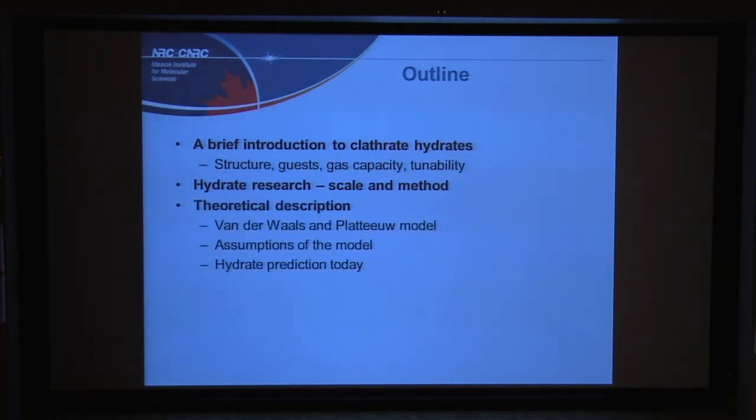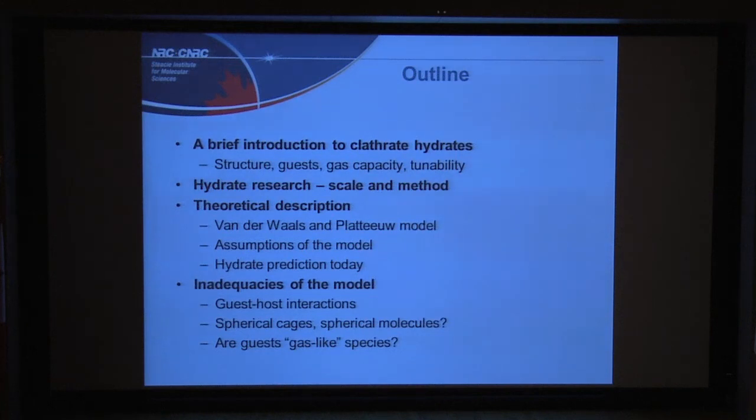Then I'd like to get on to the theoretical description. The van der Waals and Platteeuw model dates back to the 50s, and we'll look at some of the assumptions of the model and how it is used to do hydrate prediction today. Then I'd like to speak about the inadequacies of the model, which various experiments and molecular dynamics simulations have shown recently.